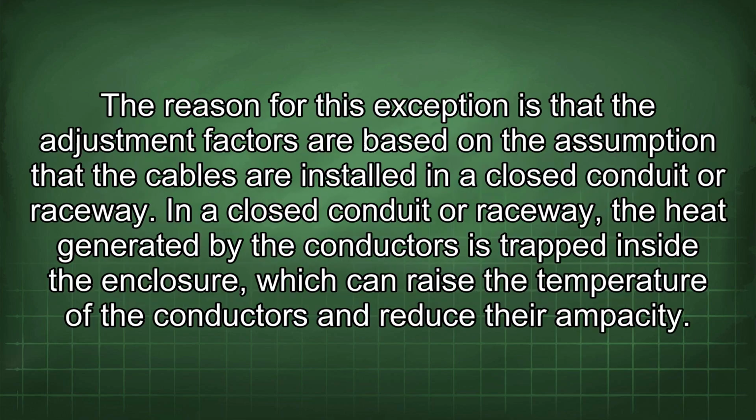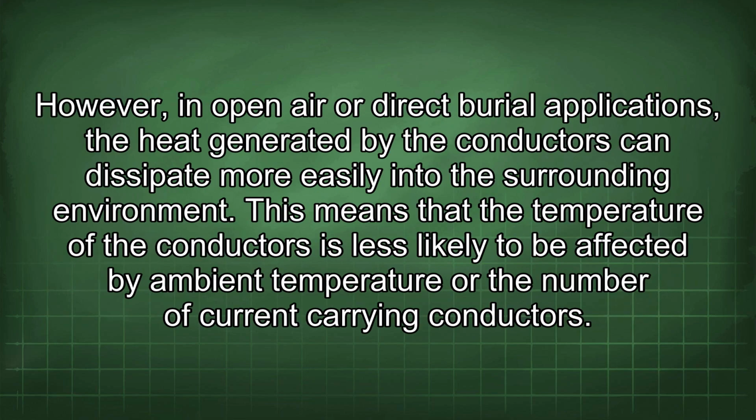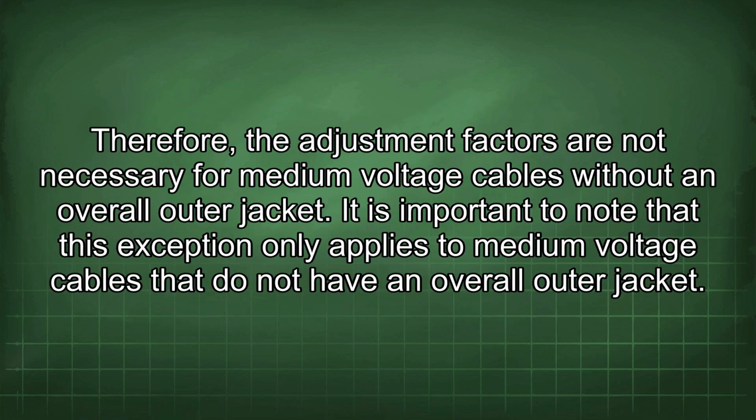current-carrying conductors. The reason for this exception is that the adjustment factors are based on the assumption that the cables are installed in a closed conduit or raceway. In a closed conduit or raceway, the heat generated by the conductors is trapped inside the enclosure, which can raise the temperature of the conductors and reduce their ampacity. However, in open-air or direct burial applications, the heat generated by the conductors can dissipate more easily into the surrounding environment. This means that the temperature of the conductors is less likely to be affected by ambient temperature or the number of current-carrying conductors. Therefore, the adjustment factors are not necessary for medium voltage cables without an overall outer jacket.